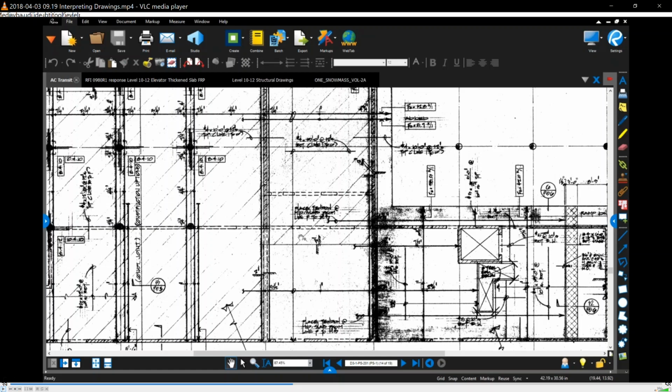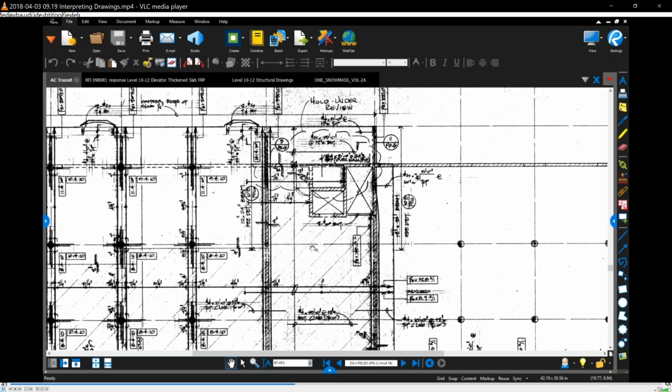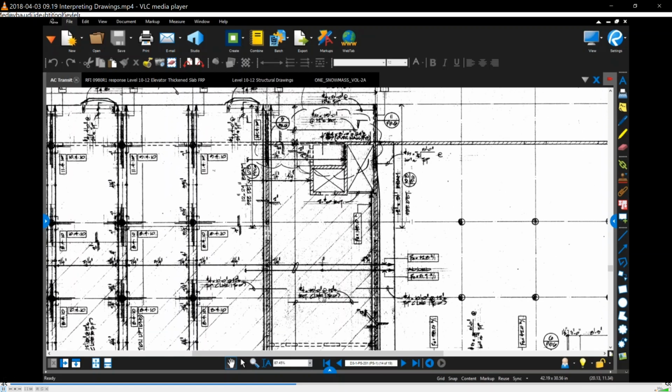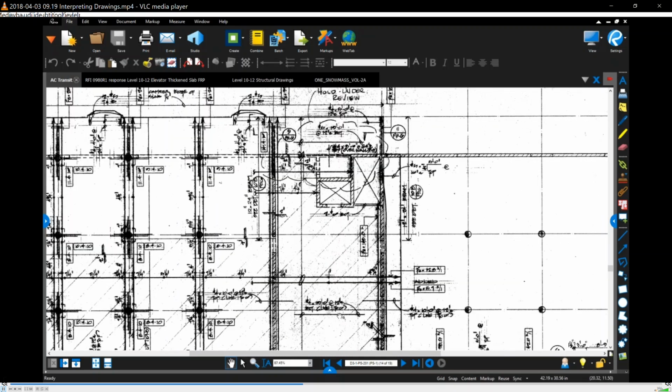So basically it's the entire bay, that's the bar. These bars are more than likely stopped at the face of this support here because this span is a lot different. And this one's even shorter, so even though the limit line shows all the way, we can pretty much bet that these bottom bars don't go into the elevator opening.